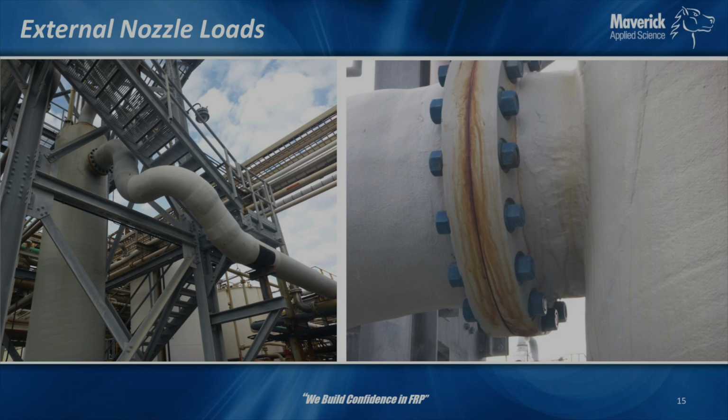Maybe I don't think that's like a shield. I'm not exactly sure. It looks almost like tape, but you have that basically sitting on steel. When you have something of this size, we find that because we do design supports, in the order of between 12-inch diameter, 10-inch diameter, we see pipes start to deflect more under their own weight, and we start to see more pipe loads where it doesn't act like a rigid pipe anymore.